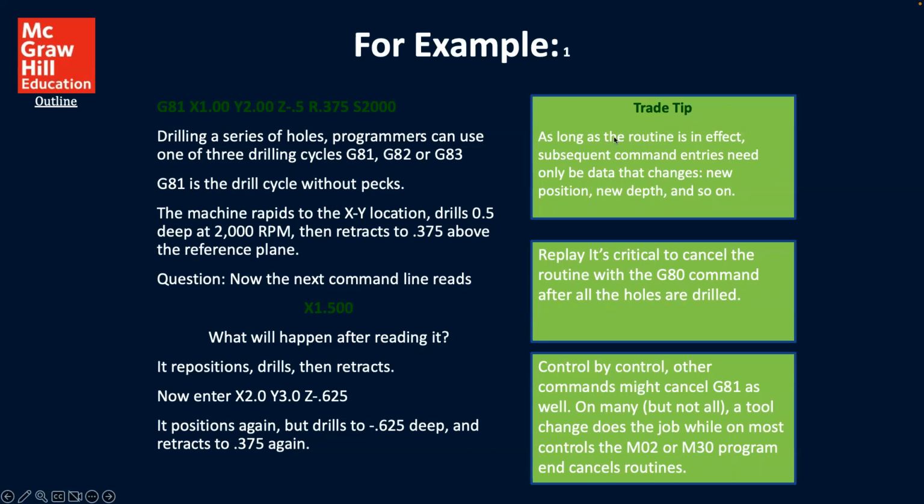And so in some ways, this can simplify the programming. A trade tip: as long as the routine is in effect, subsequent command entries need only be data that changes, new position, new depth, and so on. Repeat, it's critical to cancel the routine with a G80 command after all the holes are drilled. Control by control, other commands might cancel G81 as well. On many, but not all, a tool change does the job, while on most controls, the M02 or M30 program end cancels routines.